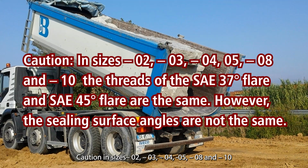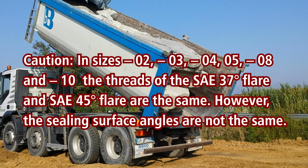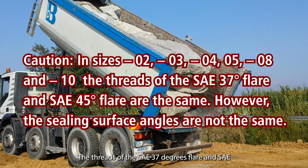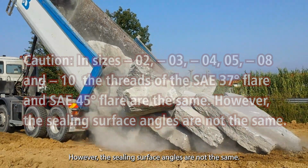Caution: in sizes 02, 03, 04, 05, 08 and 10, the threads of the SAE 37° flare and SAE 45° flare are the same. However, the sealing surface angles are not the same.